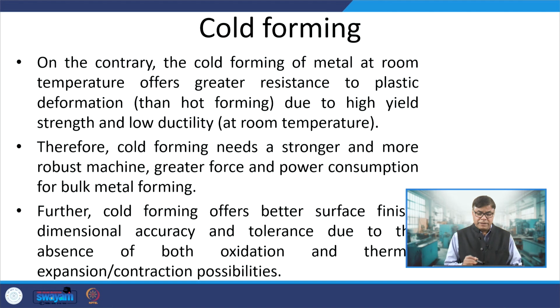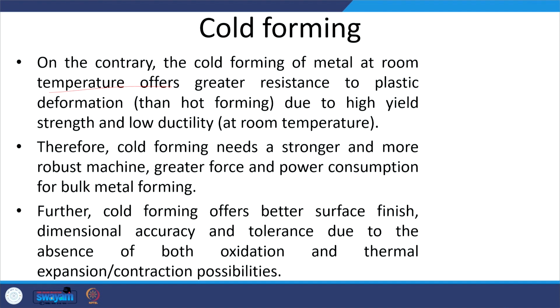Cold forming, on the other hand, is carried out at room temperature. At room temperature, since metals have greater yield strength, they offer greater resistance to plastic deformation due to the higher yield strength and lower ductility. Therefore, cold forming needs stronger and more robust machines so that heavy force can be applied to facilitate the plastic deformation.